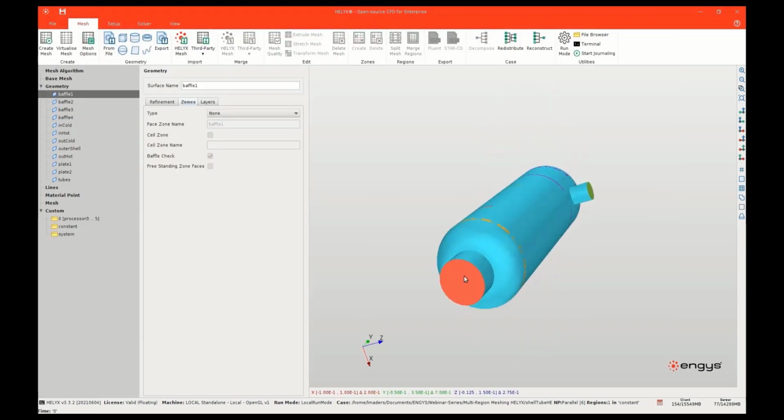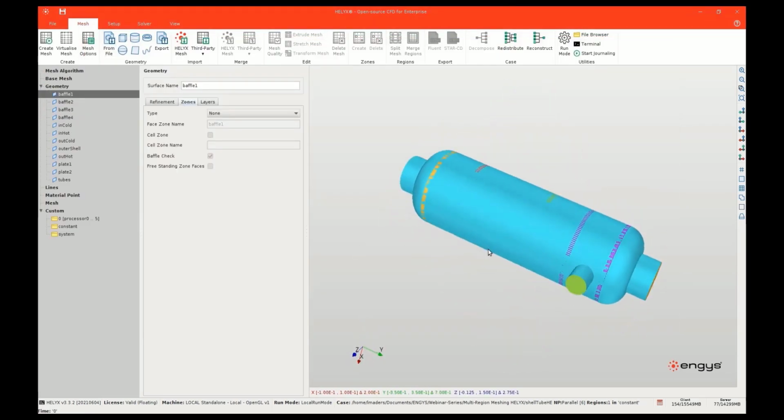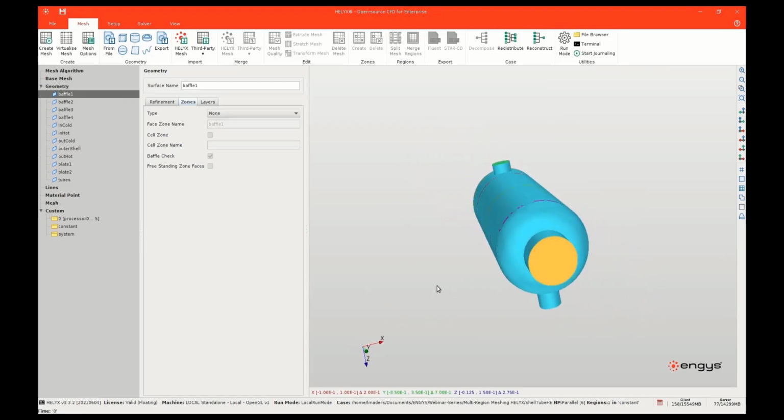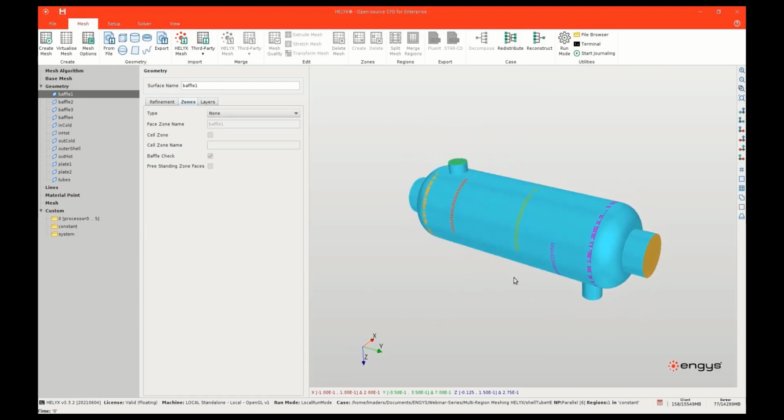And I was planning to do, as I said in the presentation, this through a zoning approach. However, since it would require that I split this geometry here in order to have one unique interface, I am going to change and do it through the material points location approach since we are running out of time.